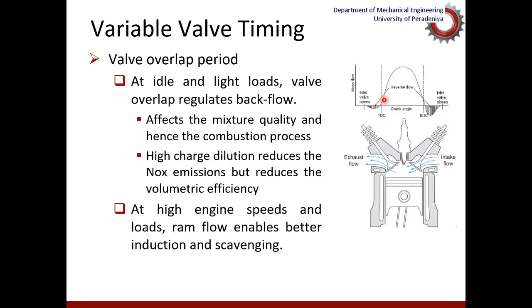And at high speeds and high loads, again, the ram effects will support the process of intake and exhaust during the overlap period. And the scavenging process, that is pushing the exhaust gases out as a result of incoming air into the system due to ram effect, would enable better performance at high speeds.